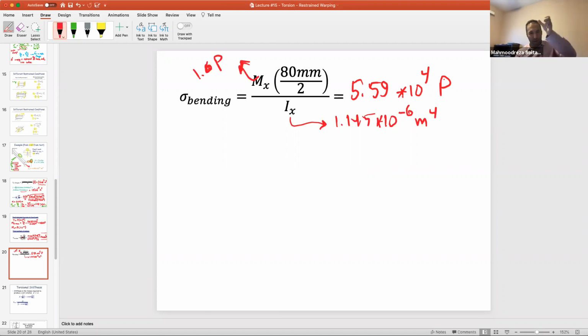One of them about y-axis. So let me show it this way. One of them about y-axis, one of them about x-axis, right? So like I show you like this. So one of them is like this, one of them is like this. Okay. So if you remember in undergraduate, we had the combination like a biaxial bending. Remember biaxial bending? So you know that these two guys, there would be one of the quarters that both of these two guys would be positive, or both of them would be negative. At that portion, it's going to hurt you. It would be the maximum. You need to add them.